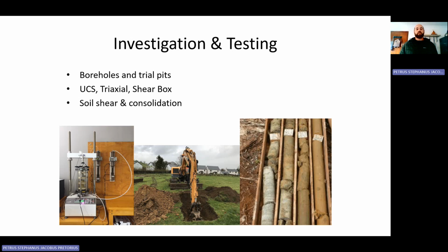Since this was a desktop assessment, I proposed a comprehensive field investigation program. This would include boreholes along the dam axis and reservoir basin, together with trial pits to confirm soil conditions. Laboratory testing should include uniaxial compressive strength tests, triaxial compression tests, direct shear box testing, tensile strength testing, durability testing, as well as soil shear strength and consolidation tests. These investigations would provide the engineering parameters required for safe foundation and embankment design.